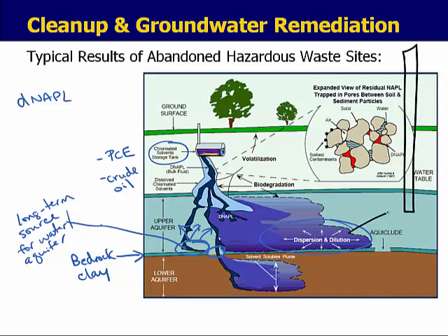This dispersion and dilution is going to reach my well and then create that human health risk for the population on top. All right, so I'm showing you two different pictures of an LNAPL and a DNAPL. The ultimate fate of the plume is dictated by the density of the fluid and the hydraulic conductivity of the subsurface. In the next module, I'll discuss some of the environmental engineering options that can be used to remediate these contaminant plumes.